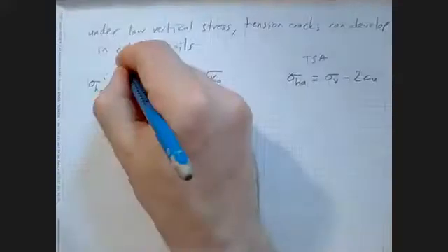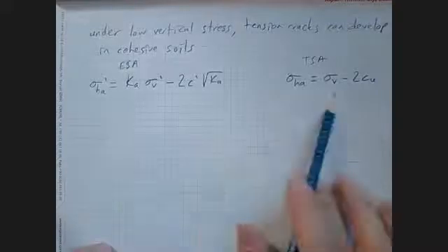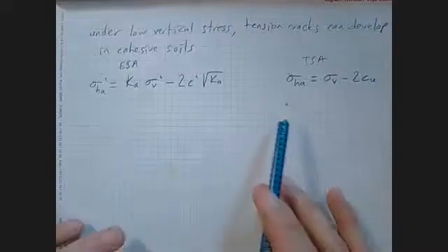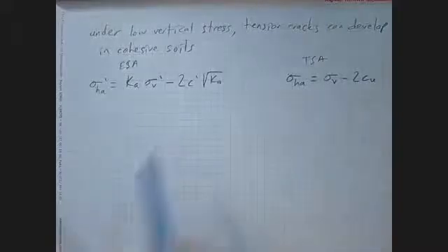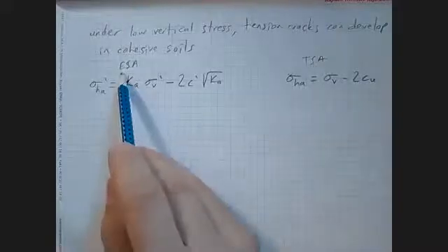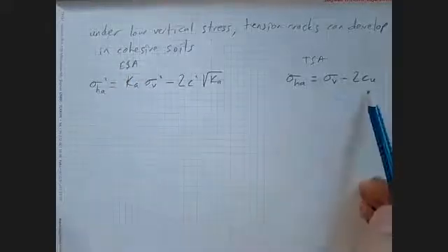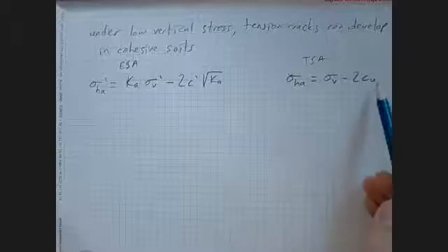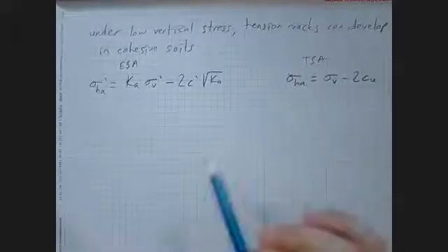I'm writing these together on the same page, but both of them won't be valid. Don't make that mistake. If you are dealing with effective stresses, this is valid. If you are calculating with total stresses, the total stress version is valid. Both of them aren't valid for the same problem.